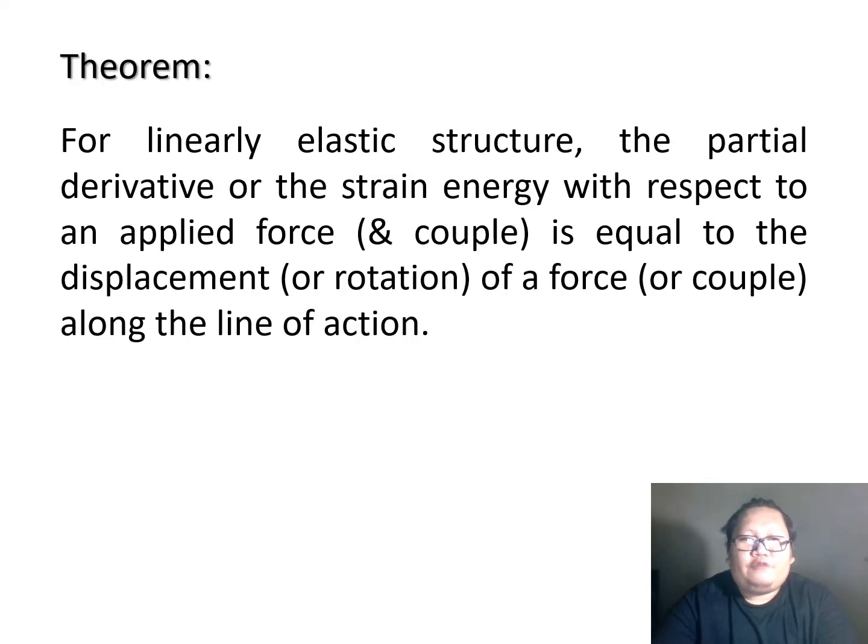Theorem: for a linearly elastic structure, the partial derivative of the strain energy with respect to an applied force or couple is equal to the displacement or rotation of that force or couple along its line of action. So it's actually just the same as the virtual work method, but this time we're going to partially differentiate the equation of a certain structure in which deflection and rotation or slope are being asked.